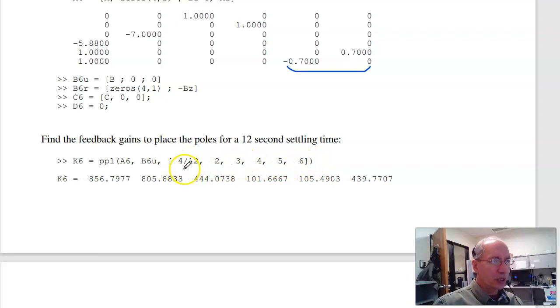Let's go over here and change my control law. So now it's the Kx, Kz that I found for the augmented system with the servo compensator having poles at plus minus j 0.7. Kz, my servo dynamics, poles at plus minus j 0.7, the servo's input, whatever makes it controllable, and now the servo has two states. Same as before, my reference is a sine wave. Here's the input, the plant dynamics, the servo dynamics, integrate everybody, plot.